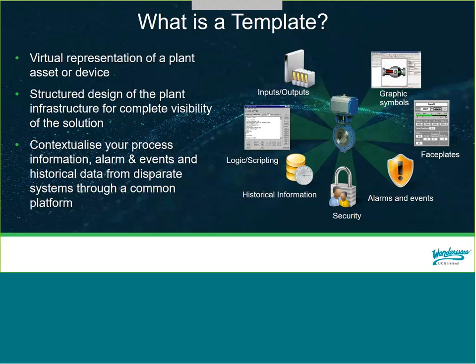So then, based on that object-based design, what we're talking about here is designing templates. So templates represent assets. In the middle there you can see a pump as an example. And it's really just a virtual representation of a physical device or asset. So the difference here is that we're associating everything alongside that. So when you create a template, you associate any inputs and outputs to the PLC, you associate any graphics that are relevant to that particular device, any faceplates, etc., etc.